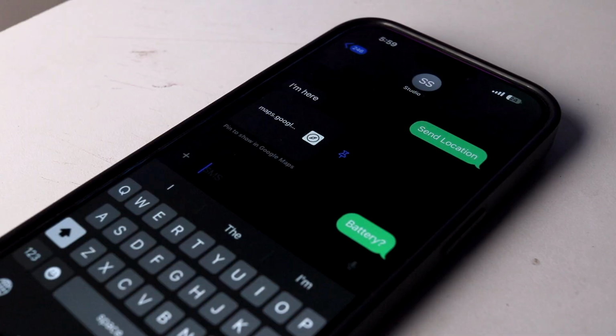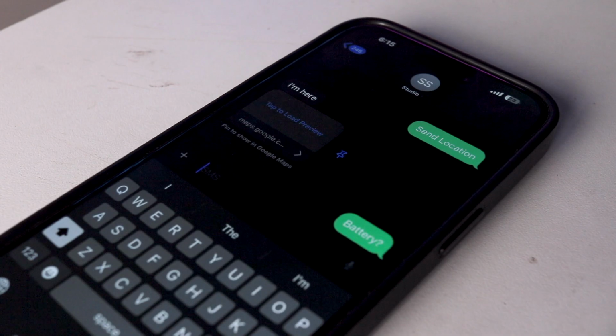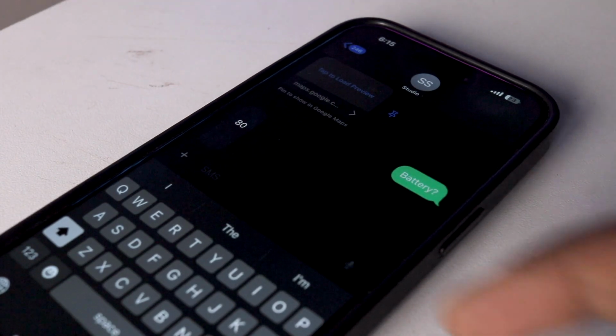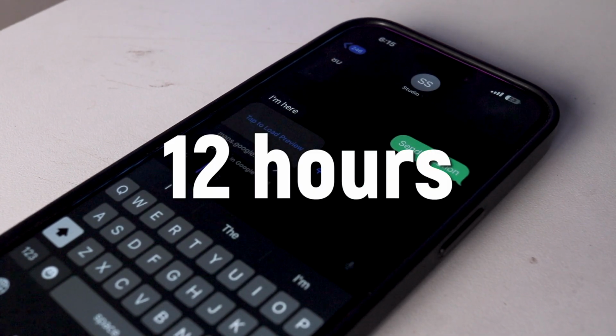Similarly, we also did testing for the second code, which was getting the location based upon sending SMS. So we were fetching the data of battery and the location every 15 minutes, and this firmware lasted for almost 12 hours on that same 1000 mAh battery. So that was the battery life, which definitely is not that awesome, but we can definitely increase it by changing the code a bit to make it more battery efficient.